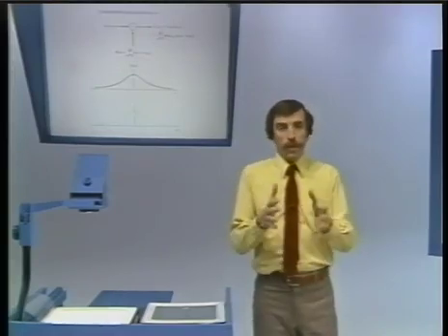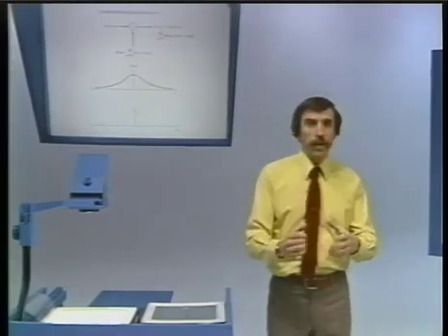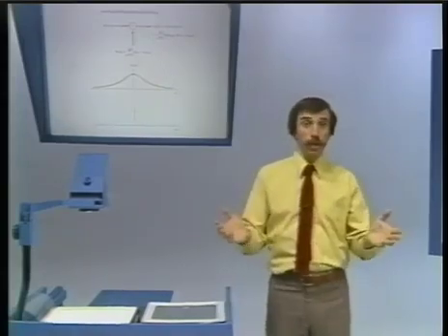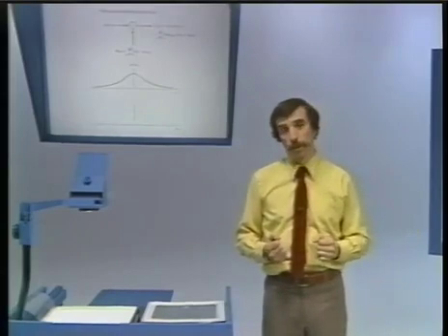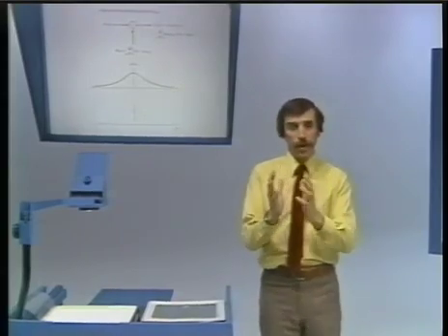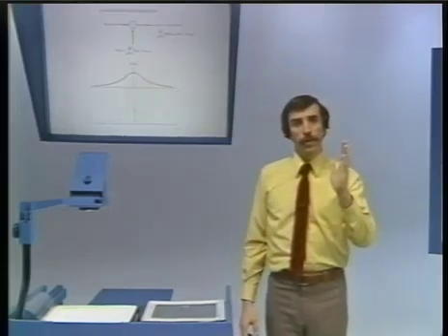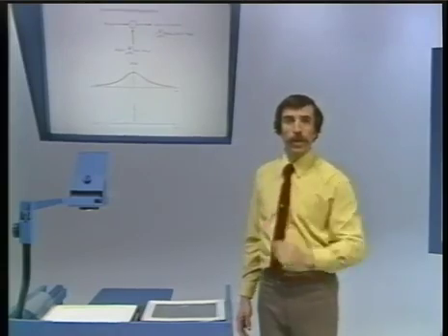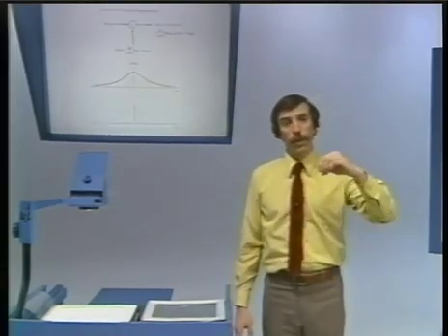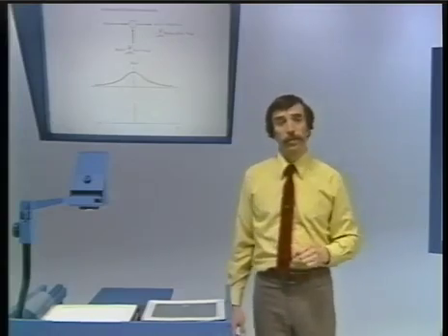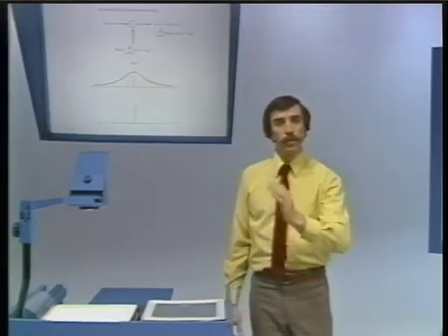Well, of course, if you want to measure it or calculate it, you can never do that exactly at every single frequency. There are too many frequencies, namely an infinite number of them. And so, in fact, all that you can really calculate or measure is the Fourier transform at a set of sample frequencies. So essentially, if you are going to look at a spectrum, continuous time or discrete time, you can only really look at samples.